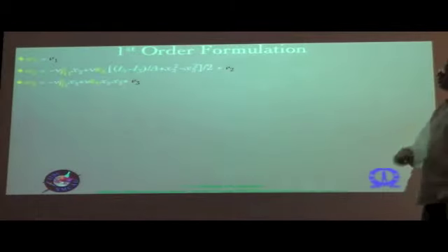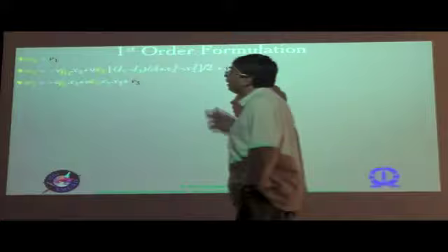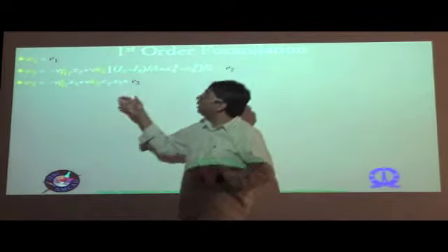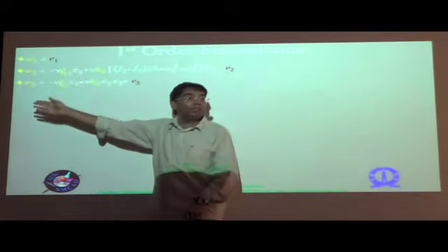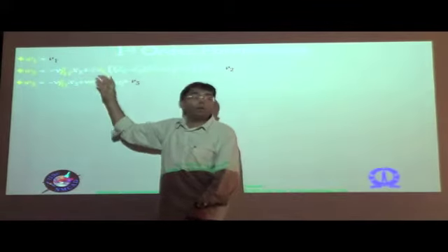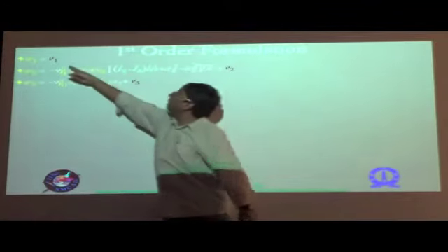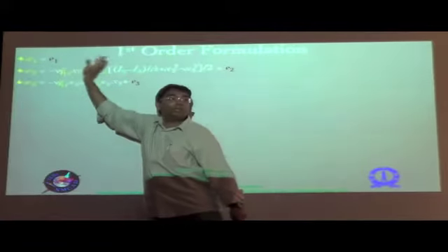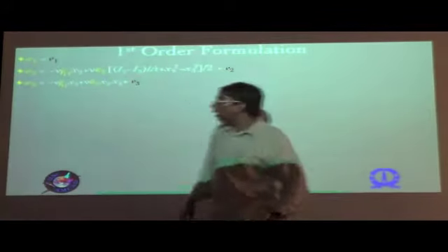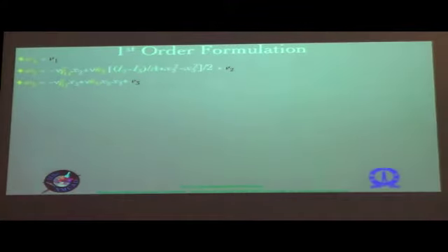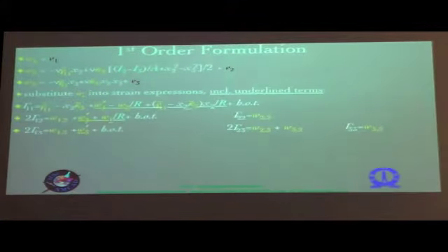With this, we go into the first order formulation. This is expanding out what we mentioned in the previous slide. Basically the three direction warpings are the corresponding W naughts plus V1, V2 and V3. These are the additional terms. Of course, the solution for W1 was 0, so V1 is all that is there for W1, whereas W2 and W3 already had solutions, and therefore you have an additional perturbation of V2 and V3.